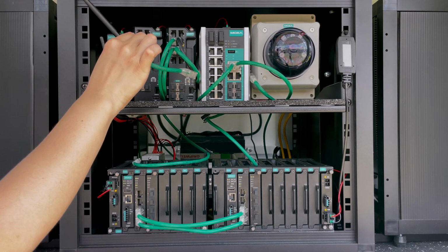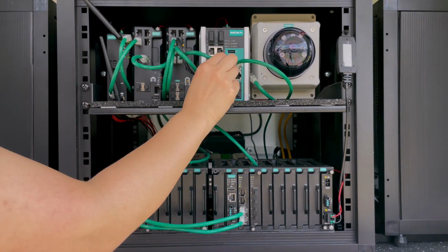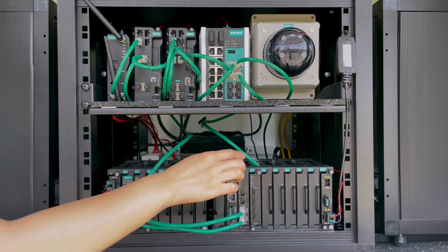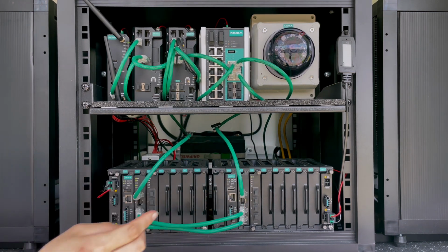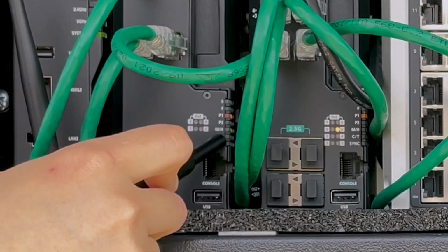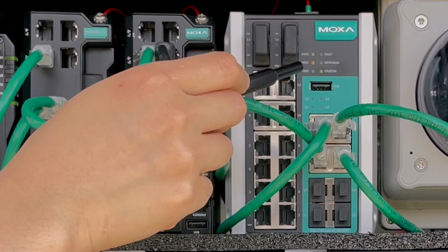With all switches configured, let's connect the cables between them using member port and hook the entire chain to Turbo Ring with head and tail port. When you see head and tail LEDs in steady green, it means that the Turbo Chain is configured properly.